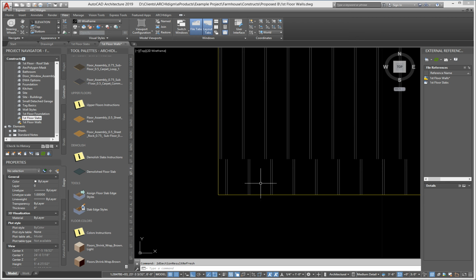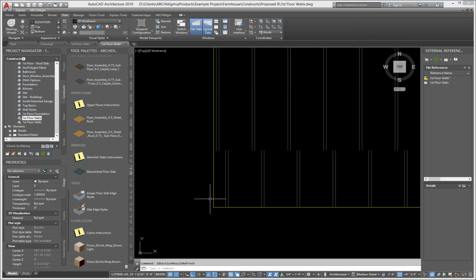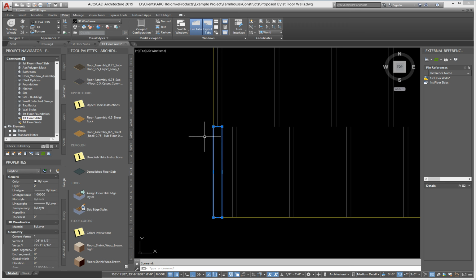So it's like you're setting the origin of the hatch pattern to here, but the way that the hatch pattern begins on a slab versus how it begins on a wall is not the same, especially if, if you recall, I added something like this much of a slab edge under the slab. So that's there, and then it starts the hatch pattern actually from there over.